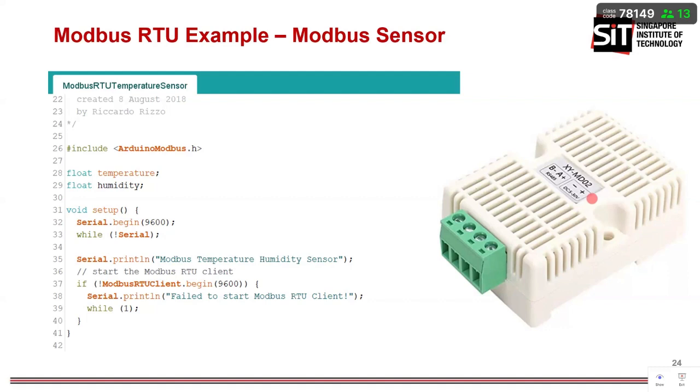In this screen that you are seeing, we are going to communicate to the XY-MD02 using the Modbus protocol. All right, we're going to make use of Modbus, and it is using RTU mode, RTU, remote terminal unit. Since this is RTU wired, it is also using RS485 wiring. Right, the physical layer is RS485. In the example code, this is the example code.